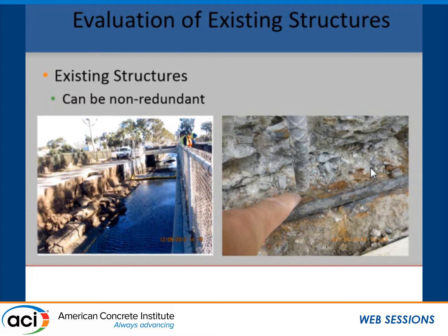Why? They probably saved about 30 cents a linear foot on the miles of flood control channels that they built, in areas that go from marine environments all the way up into agricultural areas, to areas where it hasn't rained in 2 years, and I have no idea why you need a flood control channel. They saved 30 cents a linear foot 40 years ago. Now they're looking at a couple billion dollar problem. Why? They created a structure that's A, non-redundant, and B, highly subjected to corrosion.